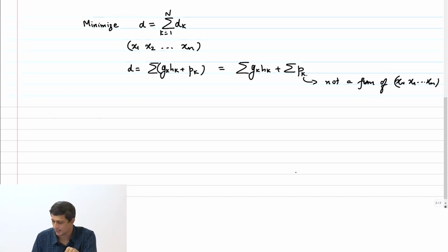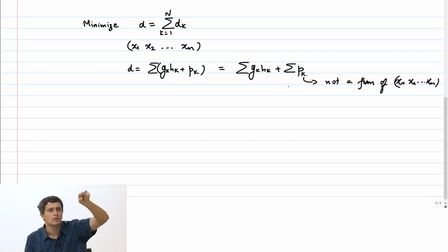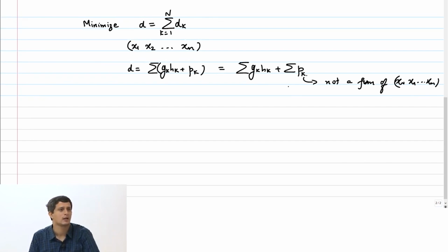Therefore, it's a constant and it is not going to alter my minimization problem. It's a positive constant. I can just remove that from my minimization problem. And this is the reason I also told you it doesn't matter whether you calculate the parasitic delay using the Elmore delay for the worst case. Whether it's 6 RC or 7 RC, it doesn't matter because it's a constant that doesn't affect your gate sizing problem. You can be more accurate, calculate with full Elmore delay or not, it doesn't matter. Okay, that's why that approximation is okay. It's not a big problem there.